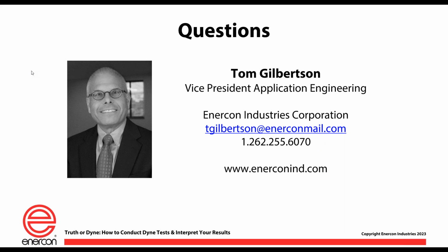Are you measuring the surface energy of this Dyne fluid on a regular basis to make sure that when you bottle it, it's going to be 38 dynes plus or minus whatever their manufacturing tolerance is? That's really what you want, right? Just because the label says it's a 38 Dyne bottle, you want to make sure that it is. And there's going to be variability. There's a range that everybody's got to account for. But that's what you want to do.